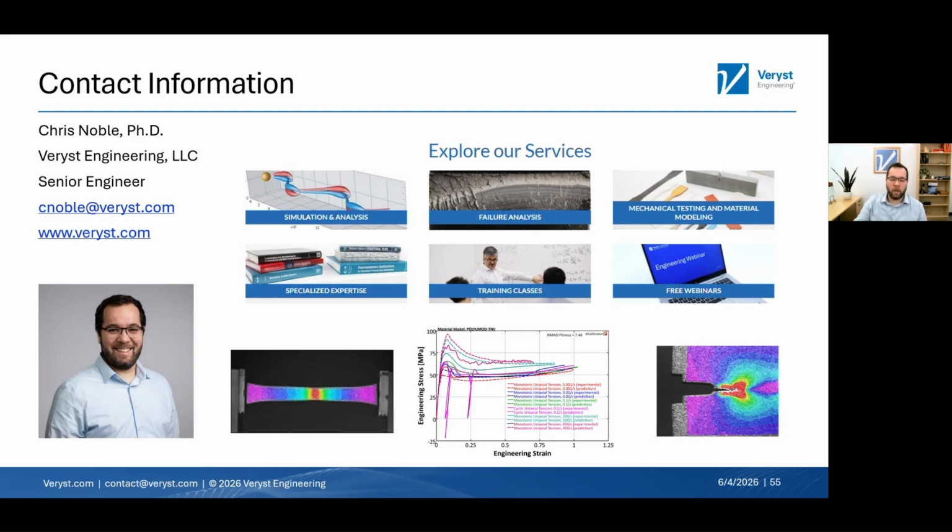You can then put that into your FEA model and optimize over the error between your indentation test data and your fabric constitutive model parameter estimates until you get a good estimate of that fabric mechanical response.